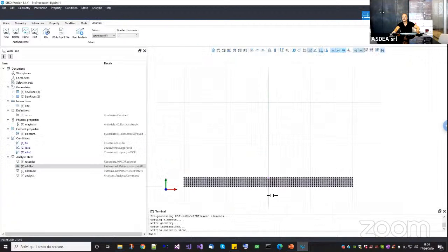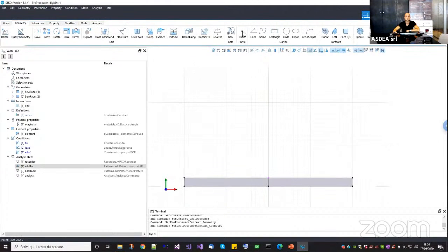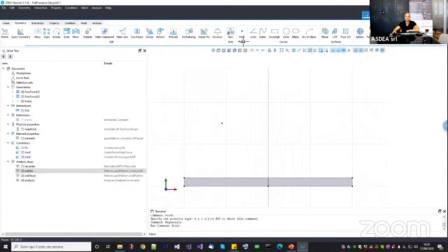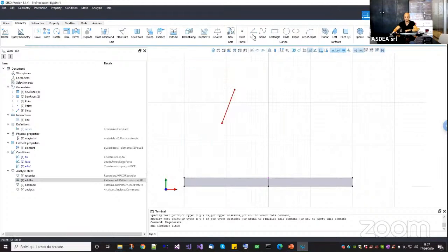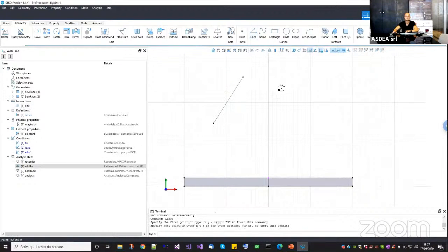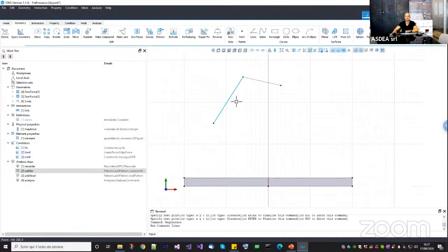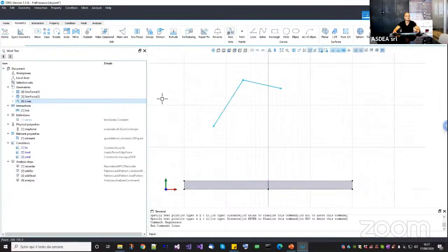because apparently it looks like the same, but depending on the Boolean operation that you have done, you can model different things. So this one is one of the main errors that I see from people. Sometimes I see something like this, as I showed you before, for frame elements. They first draw points, okay? Then they draw lines to connect them, and this is wrong, okay? If you need, for example, 2 lines connected together, you just do a wireframe like this, okay? As you can see, this one is a single geometry, so the node in the middle will be attached.